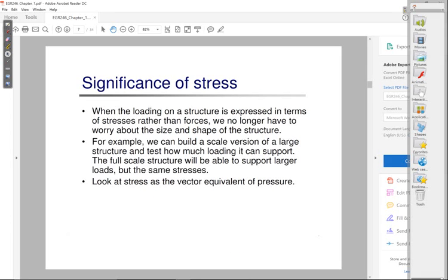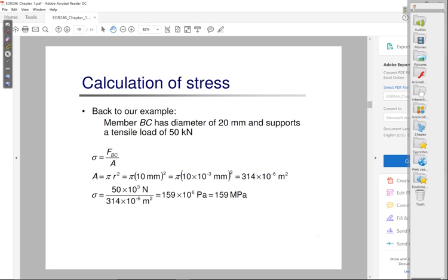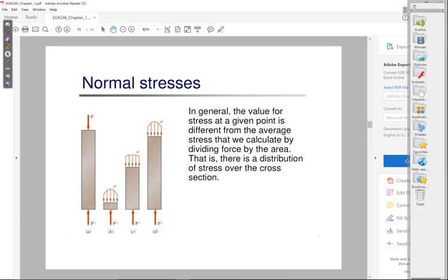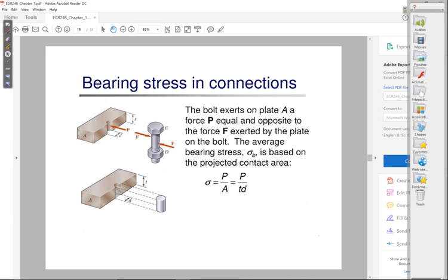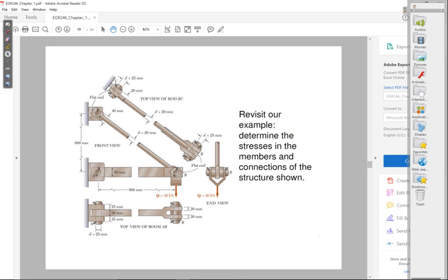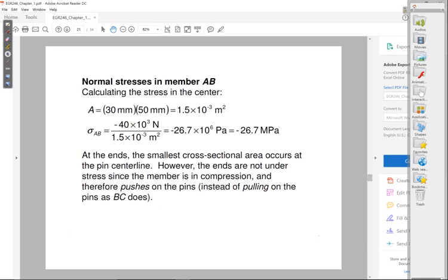And then we basically moved on to a general state of stress, right? Keep in mind that in 3D, okay, we look at a point as being a cube, right, with 6 faces, of course, 18 total stresses, but actually just 6 different stress values, okay, due to equilibrium. And then, of course, we talked about a factor of safety, okay, and why we need a factor of safety.